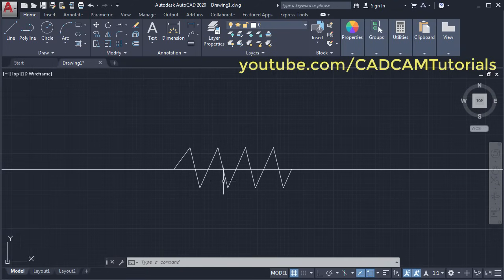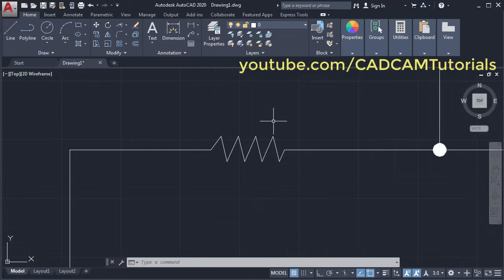Then we will have to trim this line, for that type tr, enter, then select this line and this line as a boundary line, then press enter, then click on this object, then press enter, zoom minus.